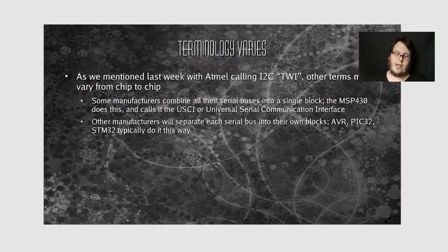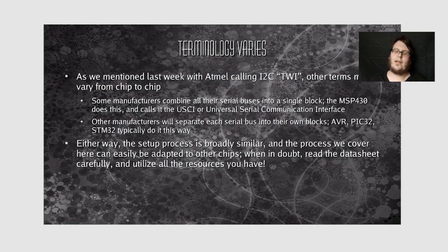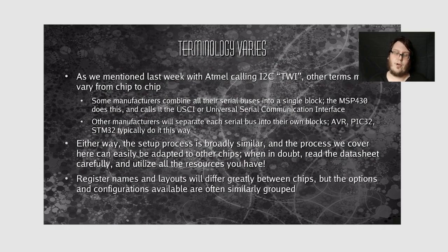Other microcontrollers will have each serial bus in their own block. This is how many other manufacturers do it. Either way, the setup process is broadly similar. There's only one difference, essentially. And the process we cover here can easily be adapted to other chips. When you're in doubt, read the datasheet carefully, utilize all the resources you have at hand. Register names and layouts are going to differ greatly, but the options and configuration bits that you are able to choose from will be similarly grouped in most cases because, of course, things go together logically.